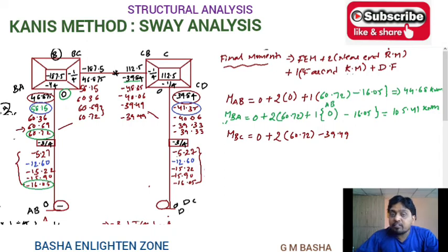Don't take the displacement factor for the beam, that is BC. So for BC and CB the displacement factor will be 0. Why? Because you won't get a displacement factor for BC and CB. The displacement factor only happens in the vertical member. Therefore take down displacement contribution only. So this is displacement contribution, sorry, not factor, displacement contribution.